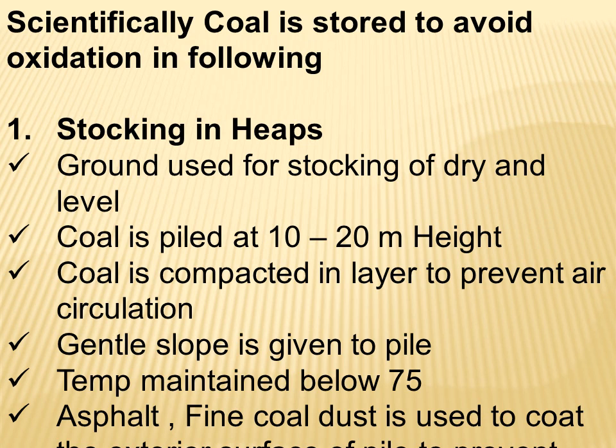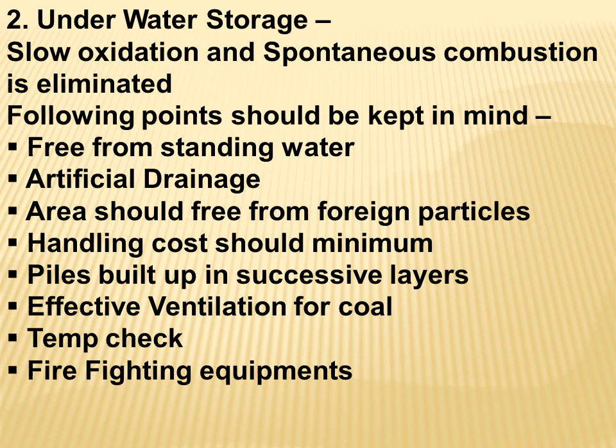Okay, that is all about the stocking of coal in heaps. This is the first method of stocking. Next, the temperature at different points should be checked, so we need to provide for it. Next, conical piling should be avoided, and firefighting equipment should be easily available at the storage site.